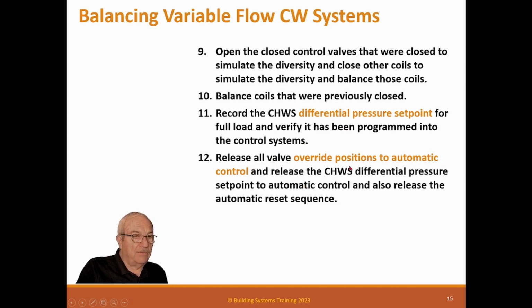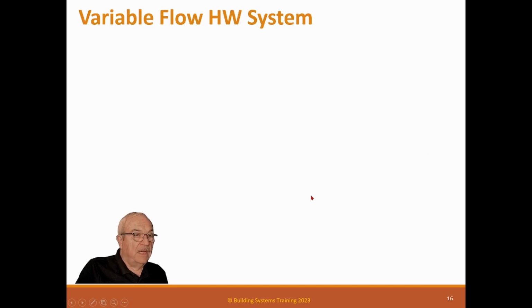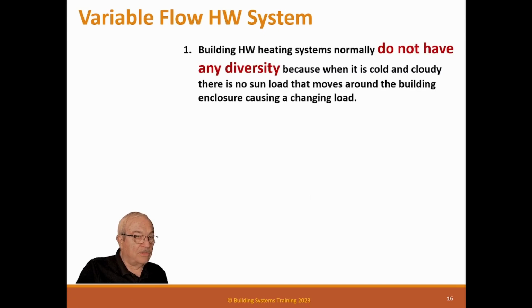We're going to release all valves, override positions to automatic control, and release the differential pressure set point to automatic control, and also release the automatic reset sequence. So that basically is how you do the chill water system. Now, what about a hot water flow system?